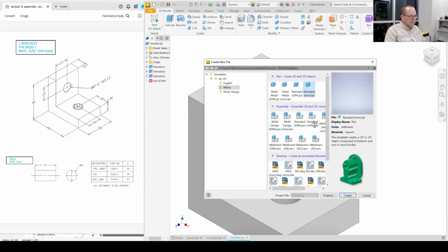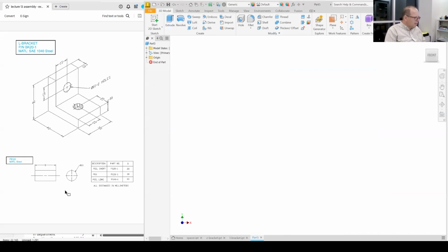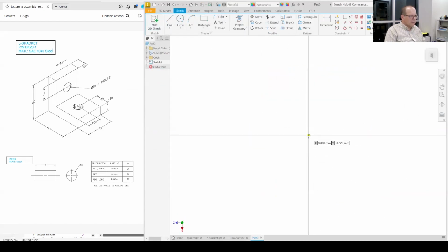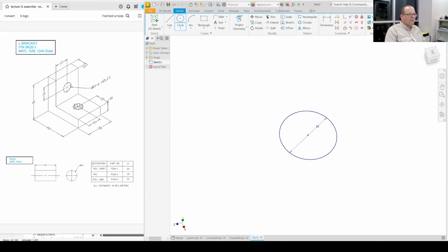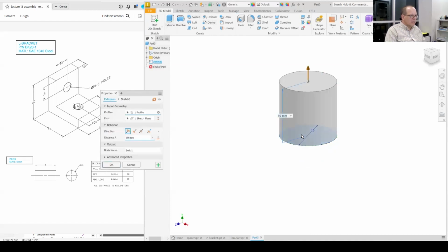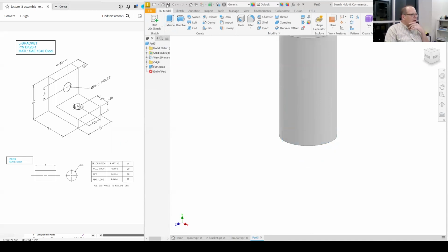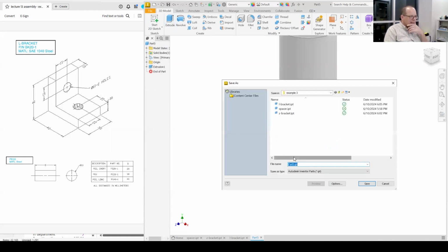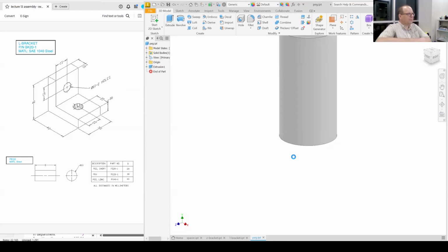And that is the peg there. It's supposed to be a length of 20. We have 10s and 10s everywhere. So let's do that. 10. Finish. Extrude to a height of 20. And we just save it, and we'll call that peg. All right, very good.